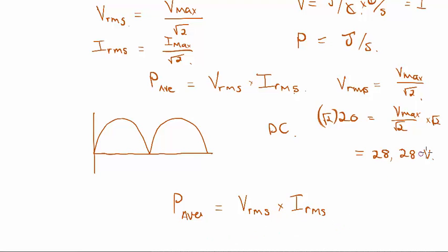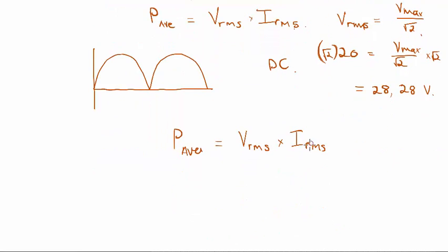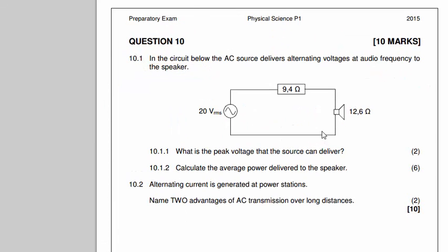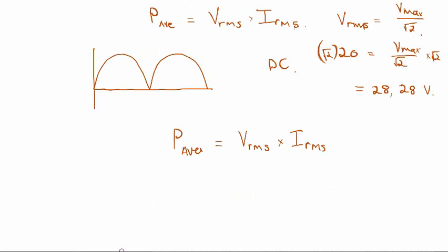Okay, so first I need to go and find the average current. I've got average volts, but be careful now. If this thing counts 6 marks, it's definitely not just finding the average current, but let's find the average current. So average current is simply your average volts divided by your resistance. You can't have average resistance, you just have your resistance.